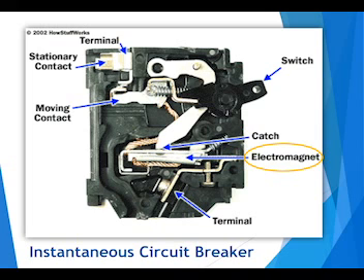The breaker needs to be in a fully off position again in order to reset the catch. But once the catch is reset, it can be turned on again and the contacts will close. We use this typically in motor control applications because it is very precise, it has a very high speed trip, it is sensitive to low overcurrent, and it is not affected by the ambient temperature.